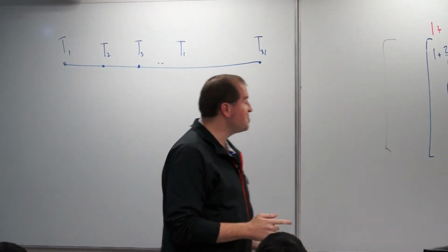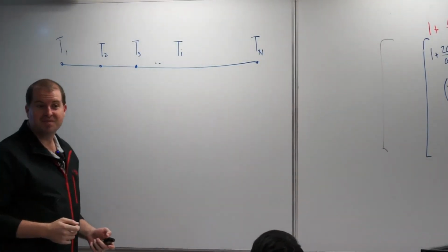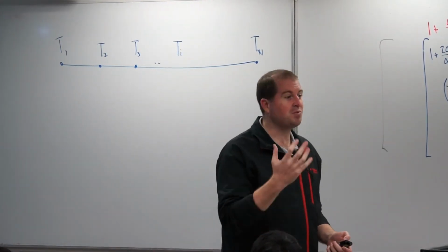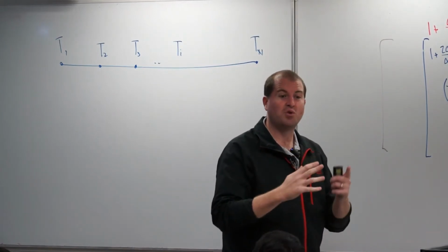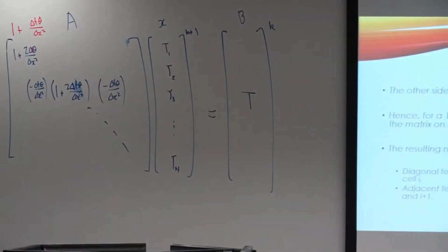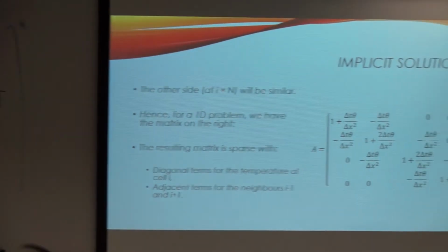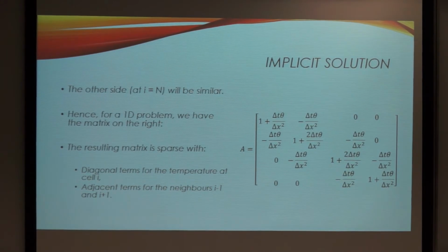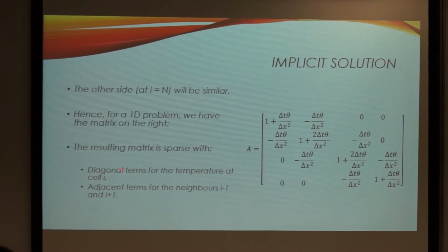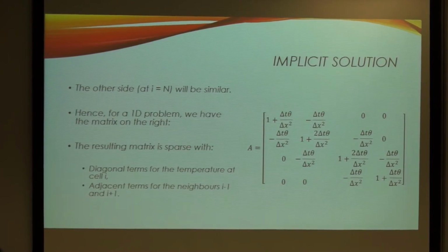If it's not symmetric, it must mean that the temperature flow in one direction is different to the other direction. In real life, this happens in composite materials and semiconductors. So if you have a special material that doesn't allow heat to flow the same way in all directions, your A matrix may not be symmetric, which is a problem because if you're going to simulate heat transfer using an implicit technique, that means your matrix suddenly is not symmetrical and you're going to have to use a solver that handles non-symmetrical terms. But for today, one-time special deal, we have diagonal terms here of the CFLs. The matrix is sparse, positive definite, and very friendly.